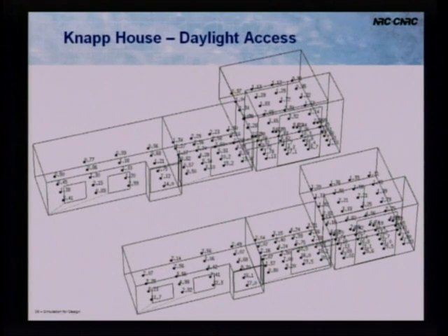Here we can see the daylight factor results. So there's a window here. The initial model with all the trees, daylight factor of 14% and 7%. Remove the trees and that daylight factor goes up to 27% and 16%. Daylight factor of 2.5 at the back of this room, which is more than adequate for daylighting. The rule of thumb, before it was down at 0.5%, so it's going to be quite dark at the back of that room.